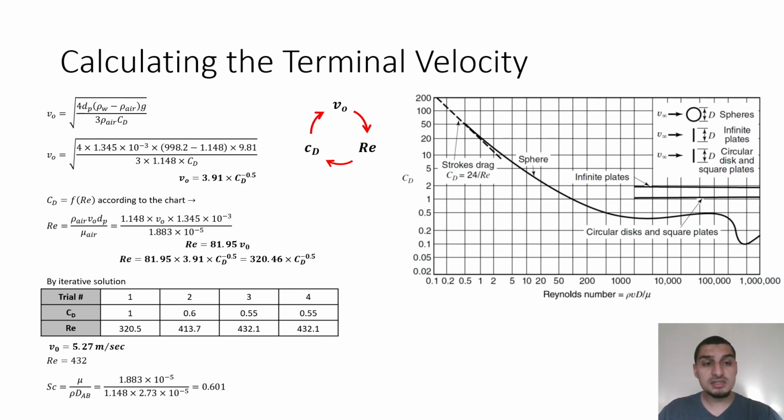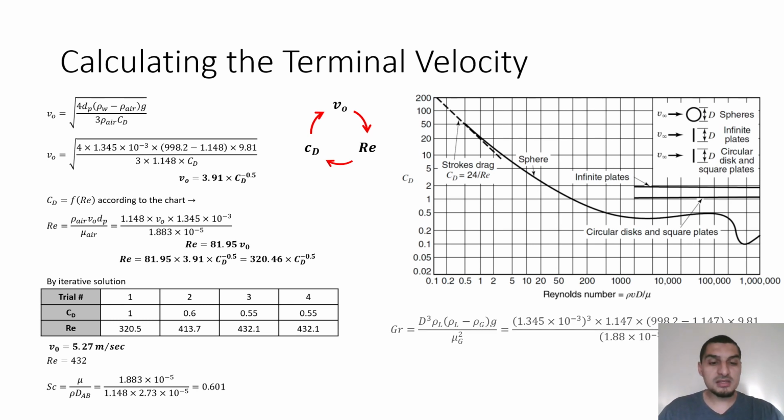You'll see here that this can be natural convection mass transfer or forced convection mass transfer. It's not clear, because I don't have anything to tell if it's natural or forced convection. So I have to do a check, and this check is to calculate the Grashof number, and I calculated it, and it is 27,905, and to calculate 0.4 multiplied by Grashof to the power half, Schmidt to the power negative 1/6.